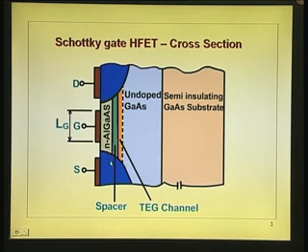What is said in that sentence is, the current transfer from the source to drain should not take place through this layer, it should take place only through this layer. So, that is possible by depleting this particular layer, and that can be depleted using this gate. So, the gate will serve the purpose of depleting this gallium arsenide layer.